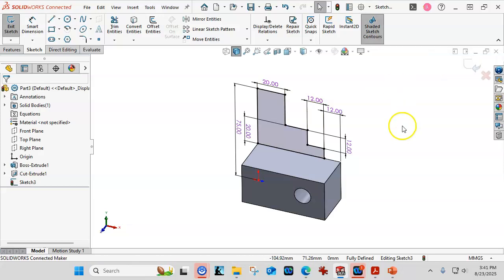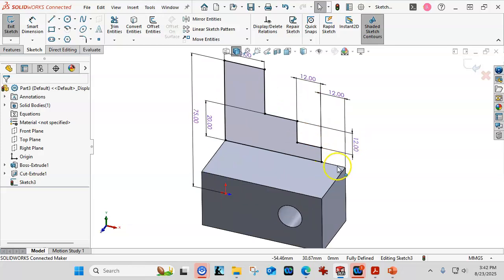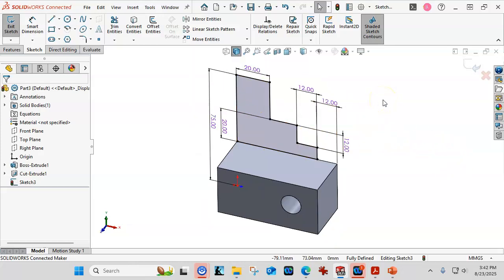All right, so shaded contours and regions. If I turn that on, it shows me that this is closed. There are two conditions where this line may be extended past, leaving a little tail, or a little bit foreshortened and leaving a gap. Those are common conditions. I hope I picked on it. But then if it doesn't highlight in the shaded contour, then it has some issue with the geometry and probably won't extrude as well as we would expect.